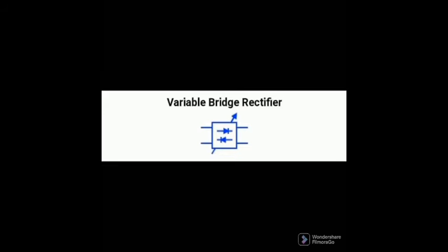Thus, this rectifier output can vary by controlling its gate input. A 3-phase rectifier converts the 3-phase electrical signal into a DC rectified output. It is a modified form of full wave bridge rectifier where 2 pairs of diodes convert each phase.